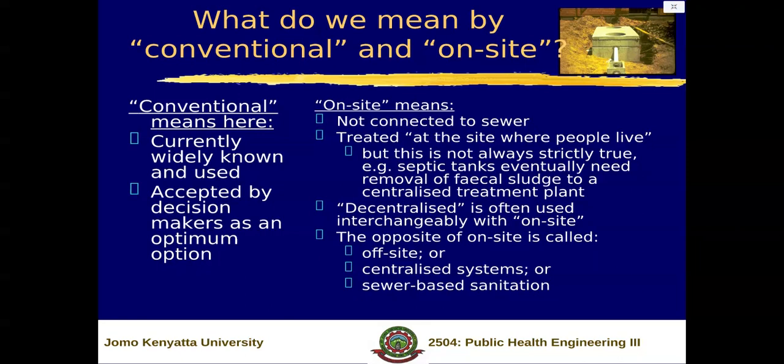But a septic tank, in the simplest way, is a primary settling tank. And so we hold water there for not more than 48 hours, preferably 24 hours. During that time, the readily settleable materials settle and the water goes to the next stage of treatment.